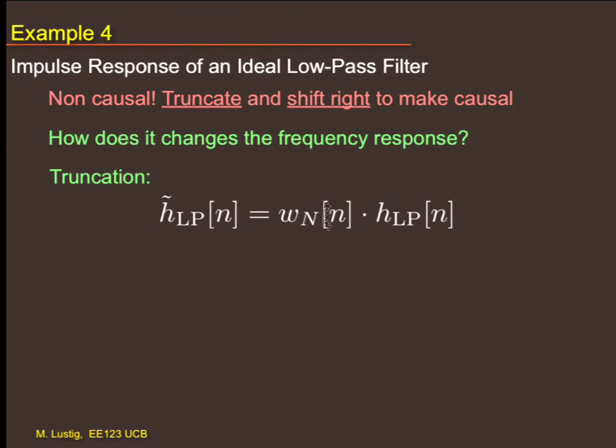We know the Fourier transform of this, we know the Fourier transform of that. This is a rect. The Fourier transform of a discrete rect is a periodic sinc. So it's a periodic convolution with a periodic sinc.